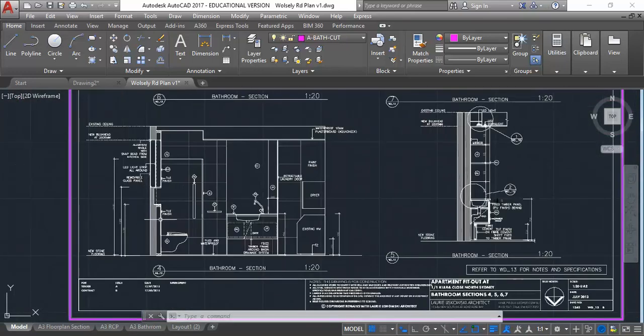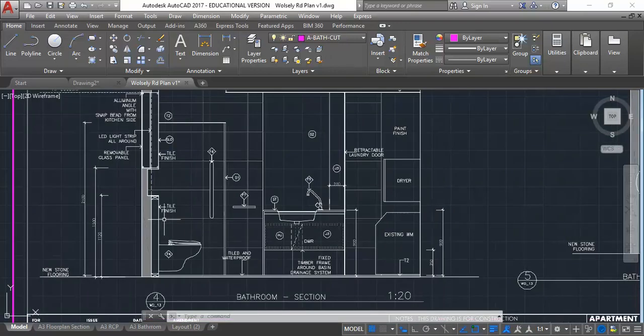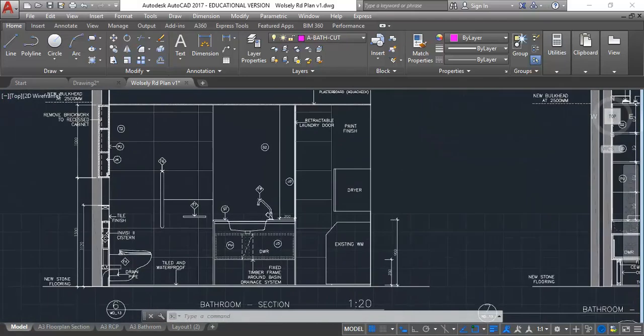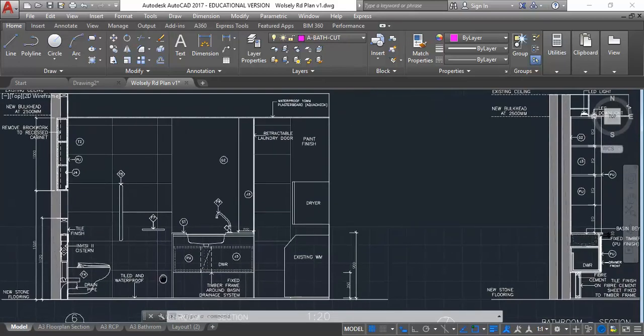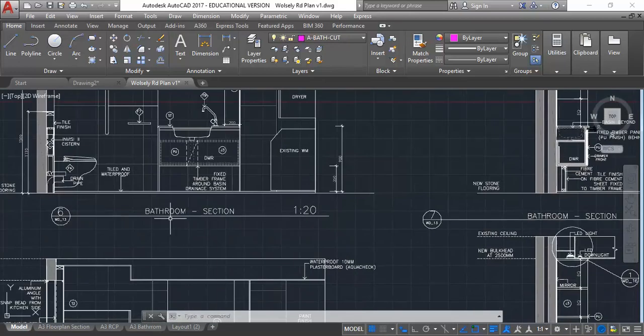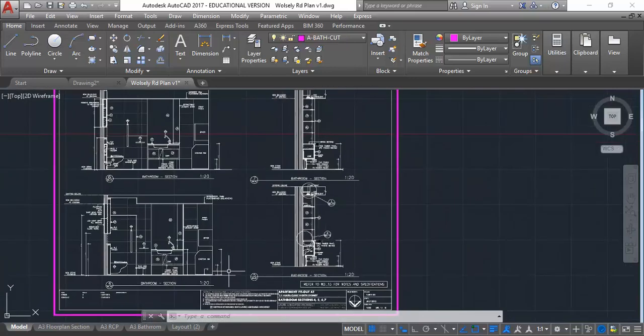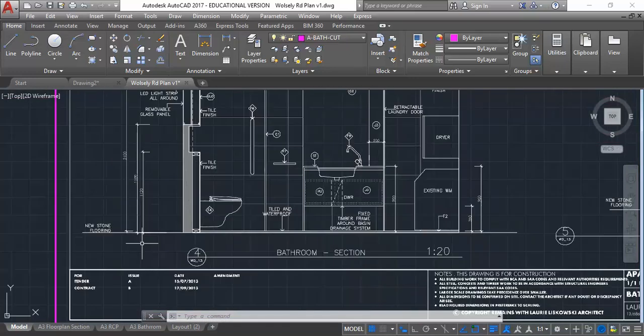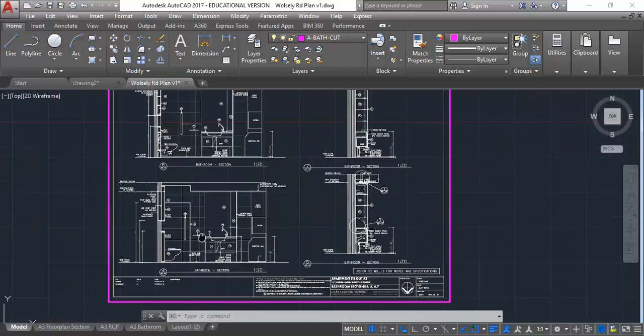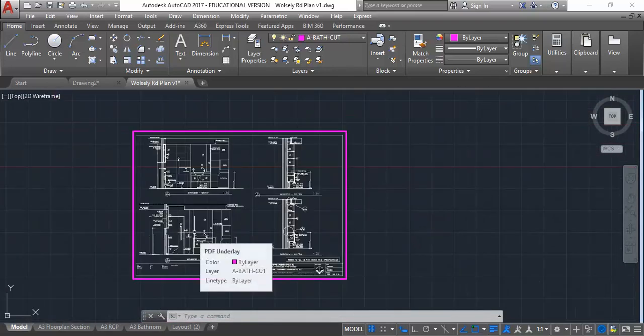Again, you can tell it's a student who was taught here the right way, and only put vertical measurements where possible on a section or an elevation. That's a really good habit to get into. And then don't have to worry so much about those issues. But again, it's good to think about that. So if you notice there's a measurement that's not right, especially if it's a measurement in a different direction, don't worry so much, as long as it's close to the right size.